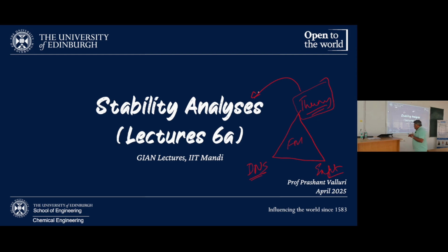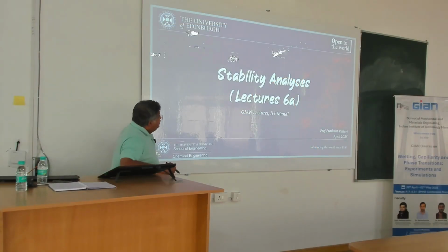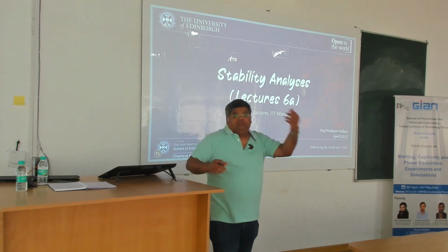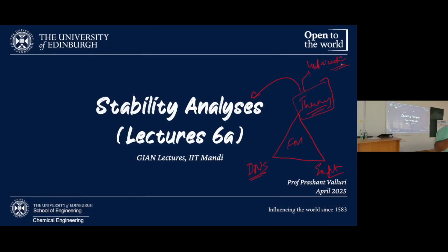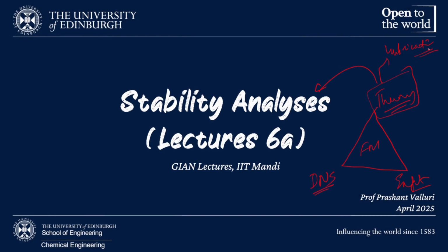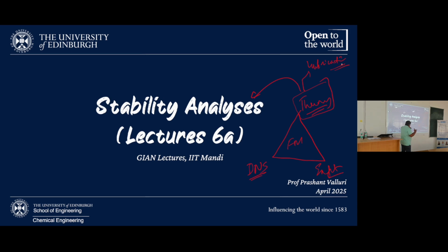Okay? There is another method which we're going to use, which is lubrication. Lubrication theory gives you some answers. It gives you the film thickness, the height of the droplet, the evaporation rates. It tells you everything. It gives you answers. But all of these are subject to assumptions, and we need to be very careful and give these assumptions a lot of respect, because in some cases the assumptions are valid, but the experiments might show that they're actually not valid. So we may have to relax those assumptions and things like that.